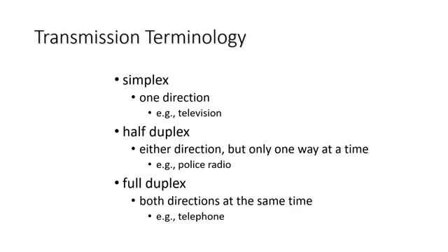Communication between two devices can be simplex, half-duplex, or full duplex. In simplex mode, the communication is unidirectional, as on a one-way street. Only one of the two devices on a link can transmit, the other can only receive. Keyboards and traditional monitors are examples of simplex devices. The keyboard can only introduce input, the monitor can only accept output. The simplex mode can use the entire capacity of the channel to send data in one direction.